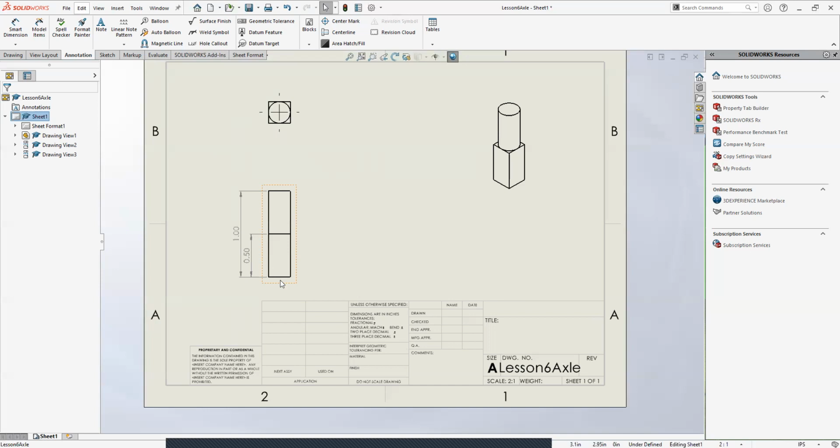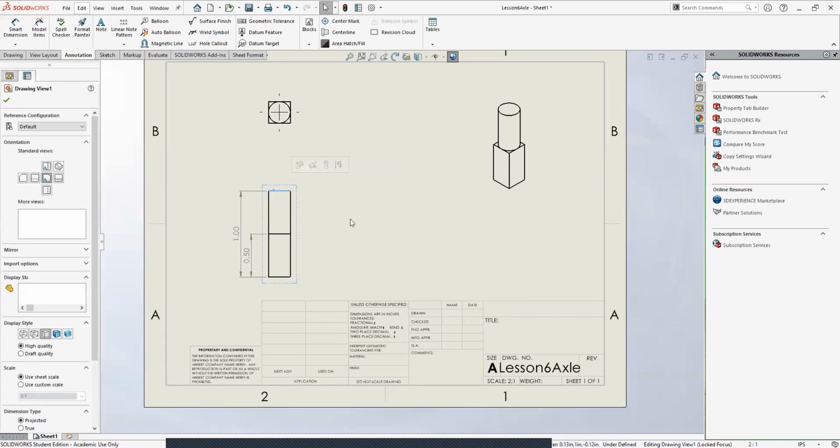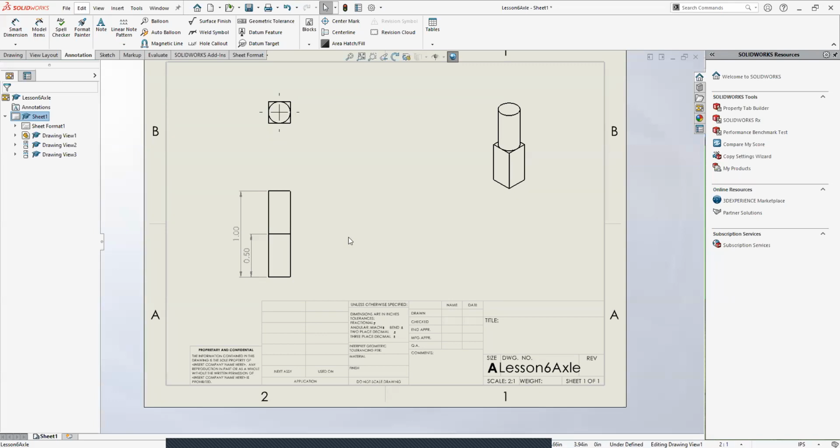The idea is we're using this as a datum or reference point. Both of our measurements are based off this line, right? Our 0.5 inches is from this line to this line. Our 1 inch is from the same starting line, but up to the top line up here. So that's basically the idea of a datum: you're picking one reference point for your dimensions.